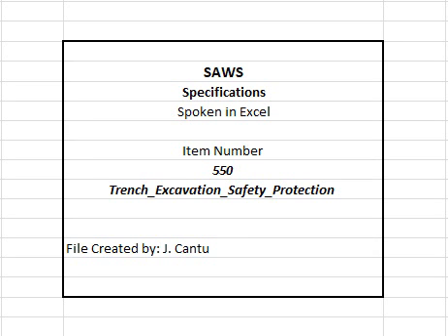2. Construction and shop drawings containing deviations from OSHA standards or special designs shall be sealed by a professional engineer licensed in the state of Texas, retained and paid by contractor. 3. Review of the safety program by engineer will only be in regard to compliance with specification and will not constitute approval by engineer nor relieve contractor of obligations under state and federal trench safety laws.